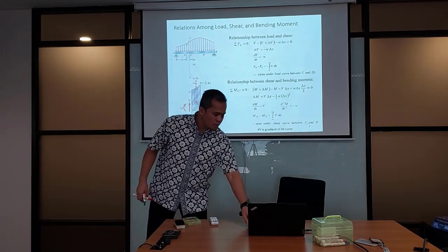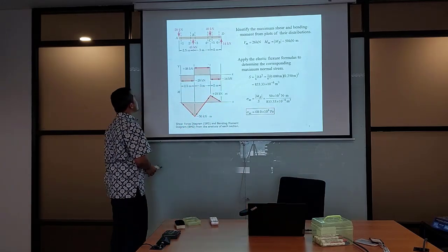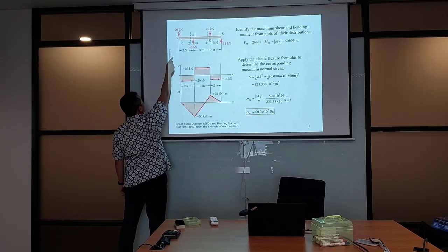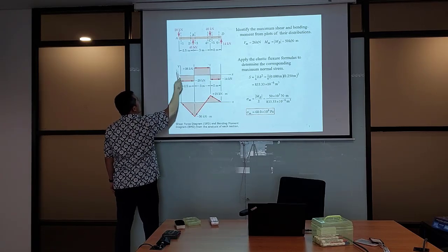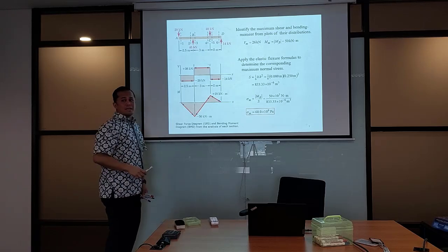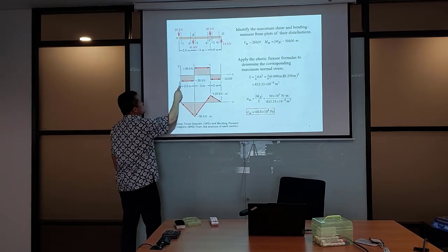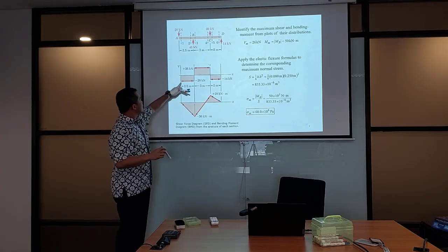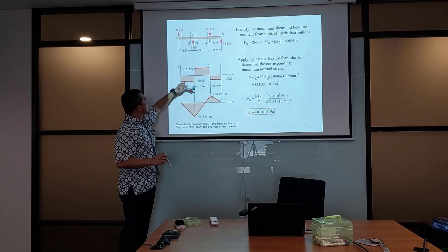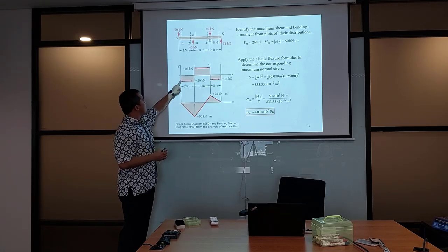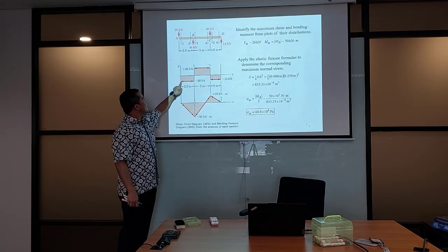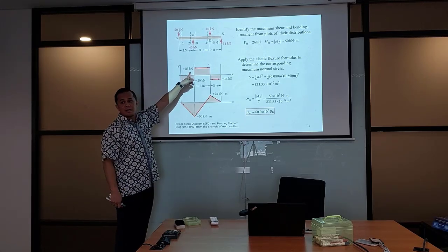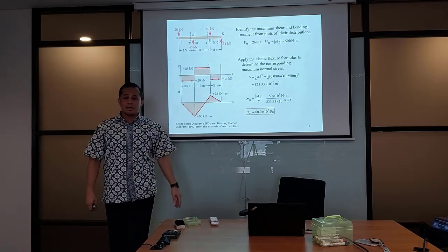So if you look at this one, the constant itself is determined by the 20 kN itself. So the 20 kN becomes the constant itself. There's no gradient though. The gradient is nothing. So no gradient, constant. No changing. 20 is 20 kN. It is going downward, therefore it is minus. Until it reaches the second applied load, 46 kN. Again, 46 kilonewton is a constant load.